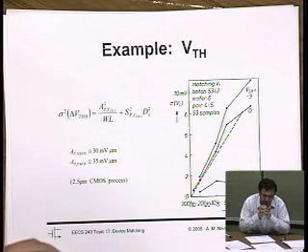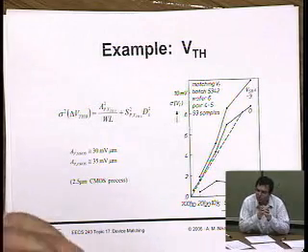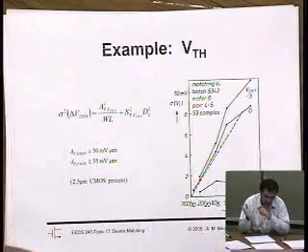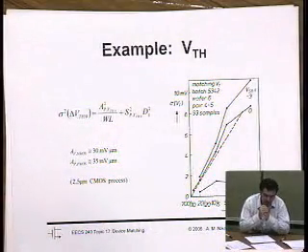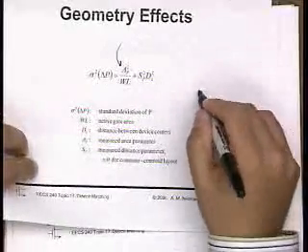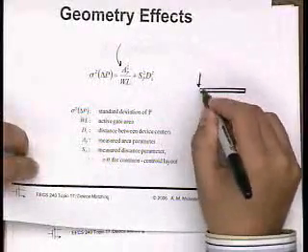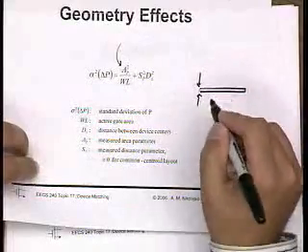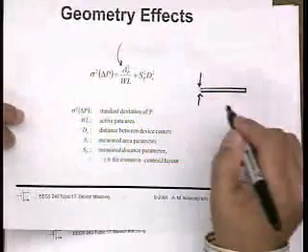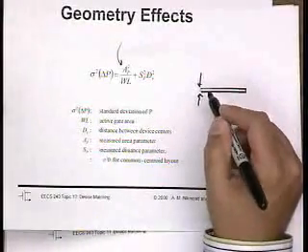At the end of the day, you're looking at what's the net charge that you could get in a region. I guess what you're arguing is that if your device has a very bad aspect ratio, then in this dimension you might in fact be dealing with individual dopants, right? You're absolutely right. In that case, the variation goes way up.